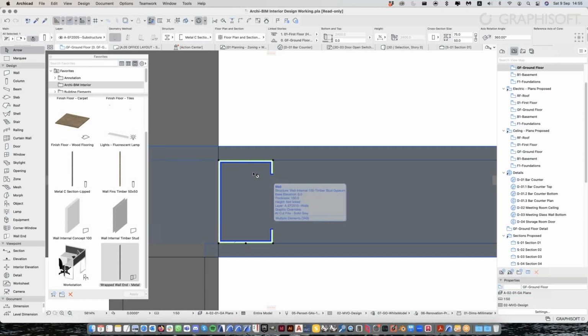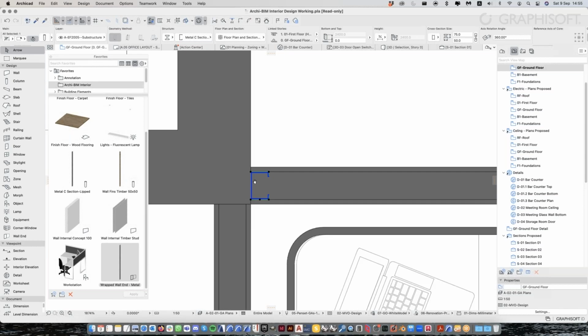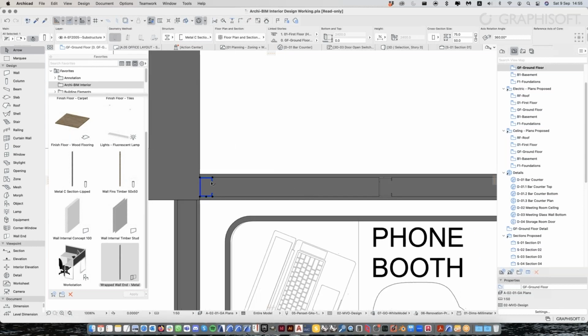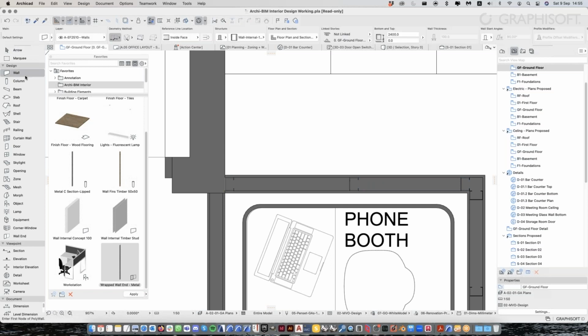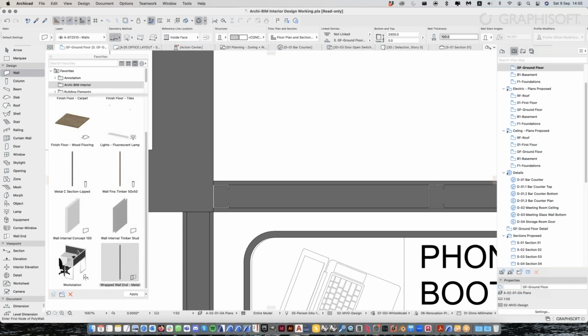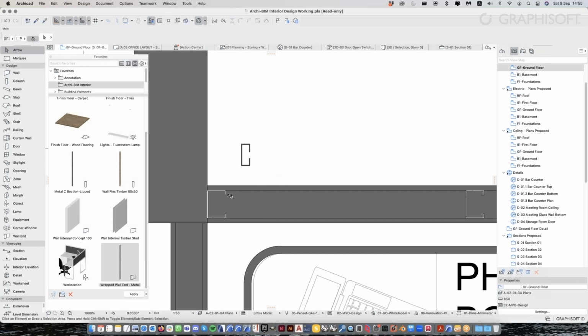It's not very ideal, because if you had to change the size of this cross section, it would not apply to the rest, right? Let's say it's just a very basic wall, and I make it like 2 mm. It's its own wall. It's not really a parametric element that you can keep editing.